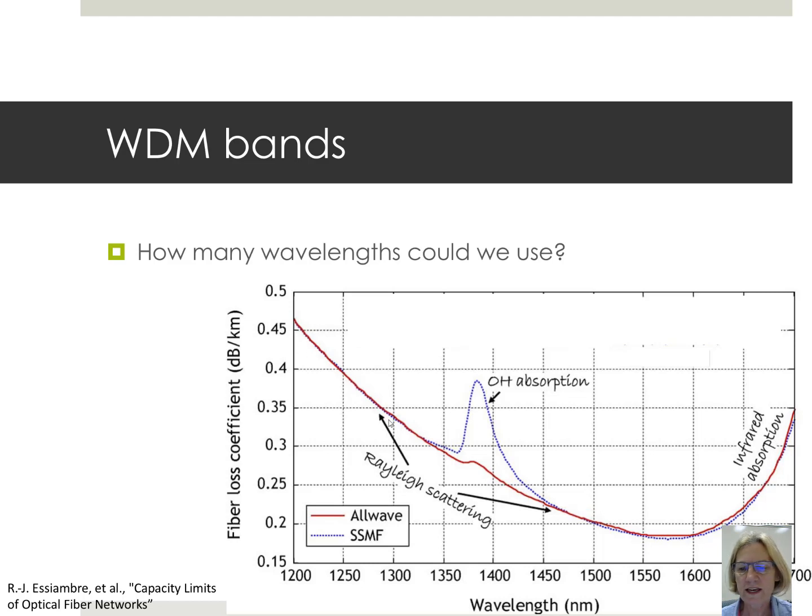But of course we can see in this graph that there are clearly some wavelengths which are much lower loss and other ones where the loss is higher. For instance, we might see in the 1300 nanometers band a somewhat acceptable loss in this range in the modern fibers, and we'll see those in shorter distance communications would be exploiting these bands.